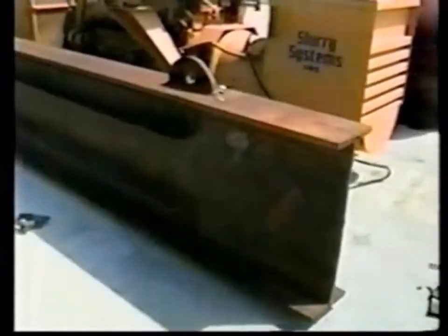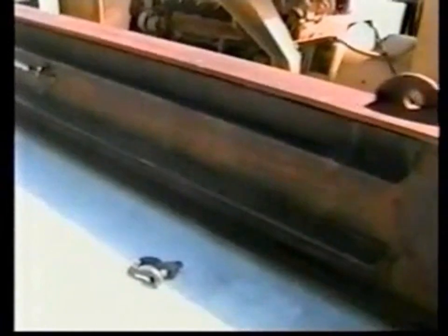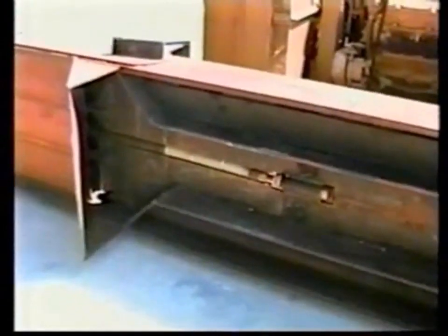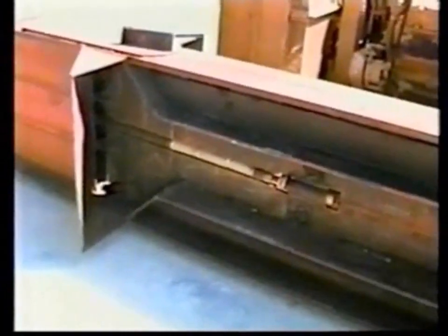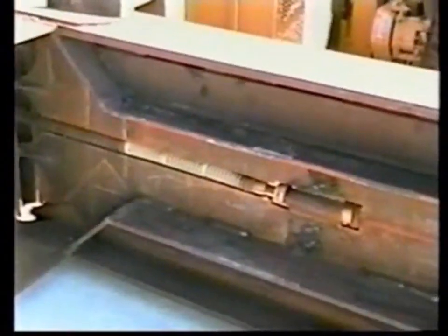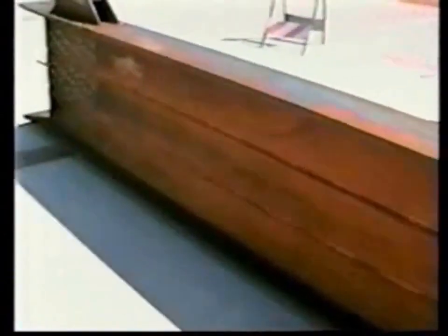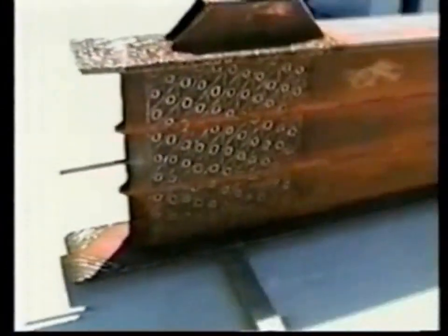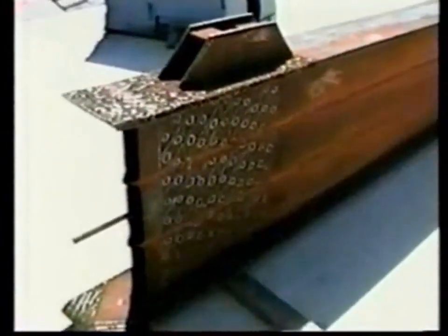The mandrel is made of 3 channel iron sections welded together with ironed end plates creating an I-beam shape. The opening at the top of the mandrel is the chute where the iron filings are loaded. A center rod extends from the top all the way to the end of the mandrel to facilitate shoe removal once the desired depth is achieved. The mandrel weighs 14,000 pounds and is over 70 feet long.